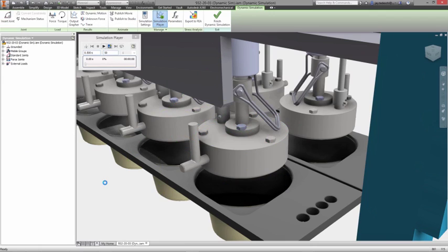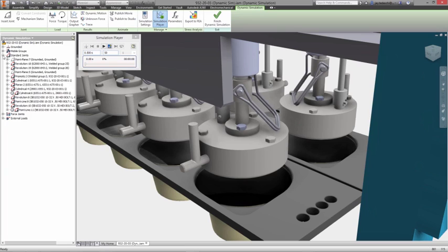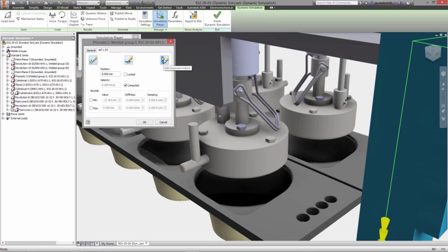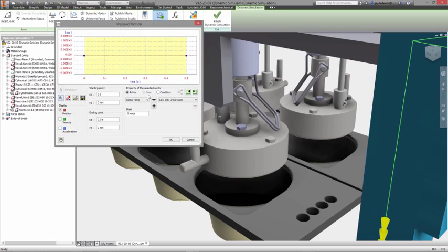From here, simply decide what information you need to derive from the simulation: an evaluation of the motion, speed, and acceleration of your design as forces are applied to it, or to understand the forces that are generated by the movement your product will experience in service. The second scenario is especially powerful, as you can transfer calculated forces into the stress analysis environment to evaluate the performance of critical components in the design.